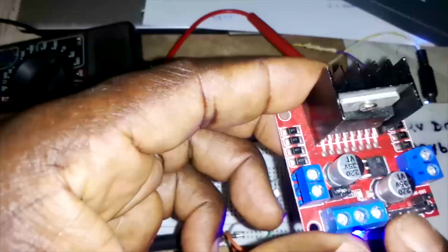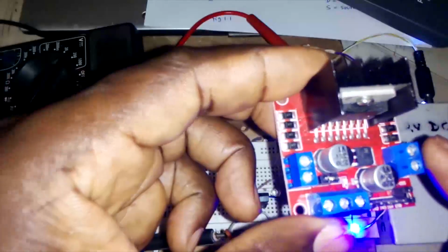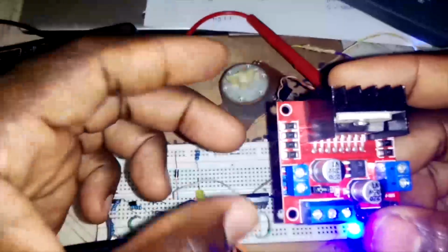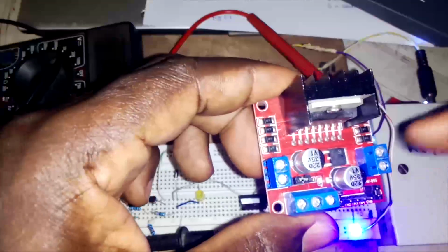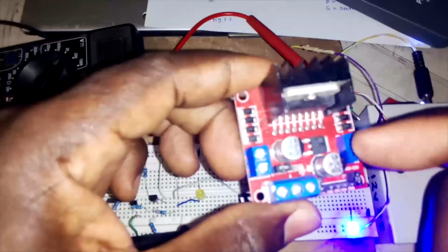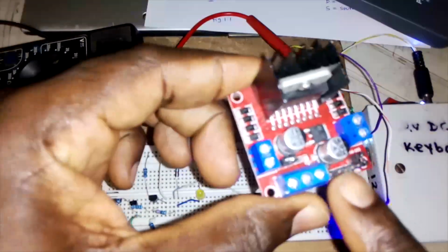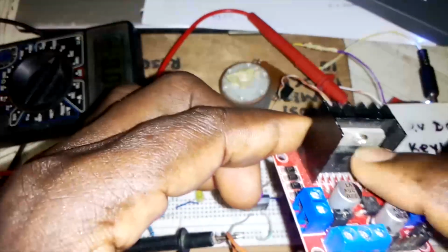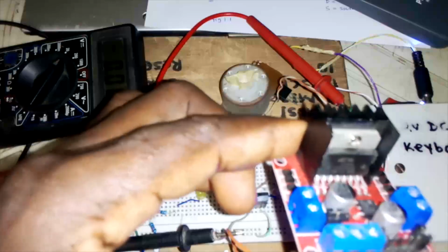These are the digital inputs that go to your microcontroller. This is where you connect your first motor and the second motor. For example, if you are going into robotics where you have 2 wheels, one wheel on this side, another wheel on this side, you connect the motors controlling each of the wheels. And then you have 4 inputs here which go to your microcontroller. So digitally, this uses an IC, an integrated circuit.